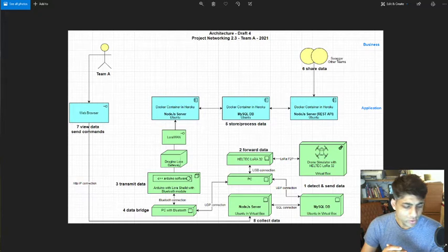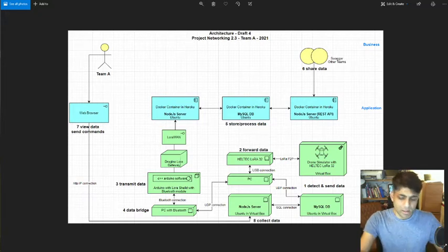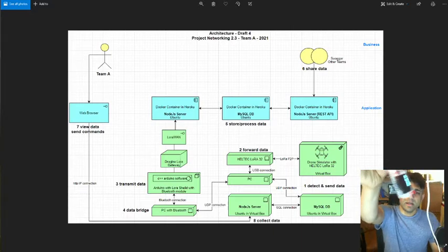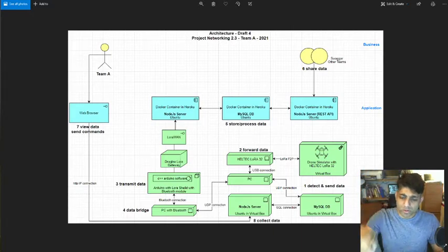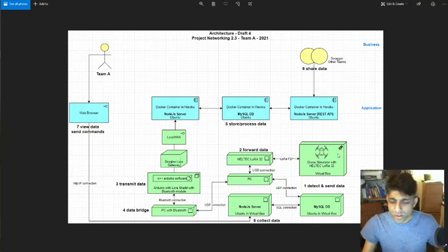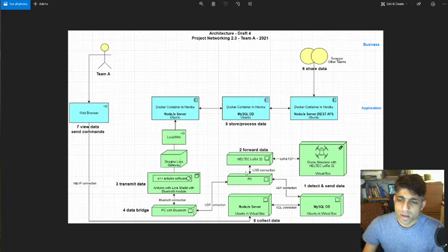So we're using a couple of Heltec devices. They are very small devices, and they connect to the TTN network. This is supposed to go on the drone, the very first node that you see over here. Then there's another one which is connected by a USB device to a computer to send and receive data through LoRa P2P. After that, the data travels.